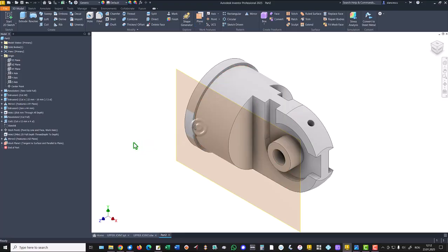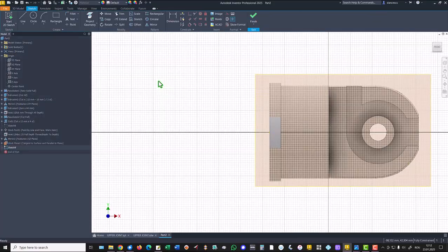Let's create this hole. Another solution than using the axis is to create a plane based on XY plane and tangent to this face for applying a point here. The point is placed at the same horizontal with the center point. Where is the center point? It is here. The distance is 25.